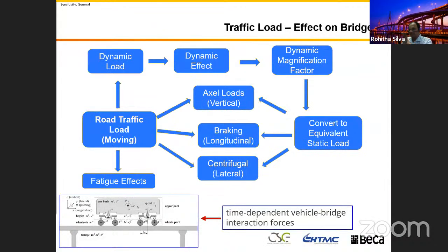So if I come back to this slide again for a few seconds, because of the dynamic effect, we need to magnify. We use the magnification factor to convert that into a static load. That's what we're going to use in our bridge modeling and bridge design.